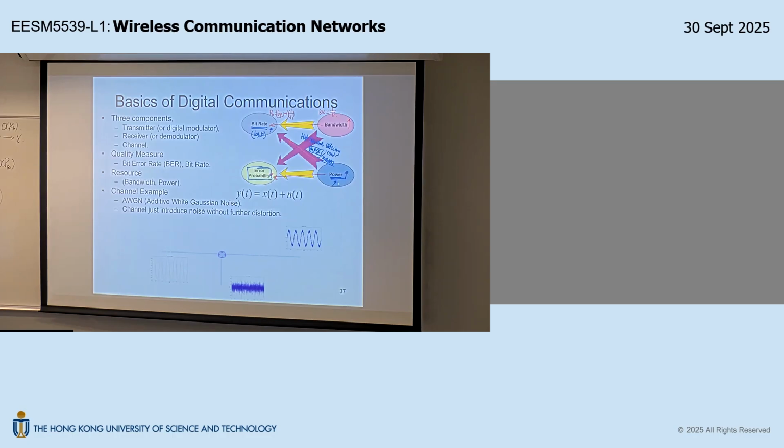So they're using higher carrier frequency, like millimeter wave frequencies. And on this, transmitter and receiver are point-to-point, and they are aligned. They are not moving. The receiver is not moving, transmitter is not moving. So in this setup, this is more like a noise limited system. There is no interference in the backhaul. So at that time, I tried to design the 4096 QAM for this wireless backhaul application.